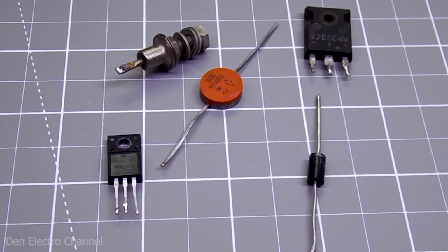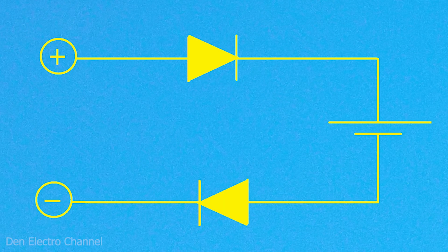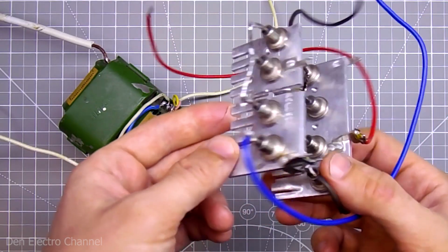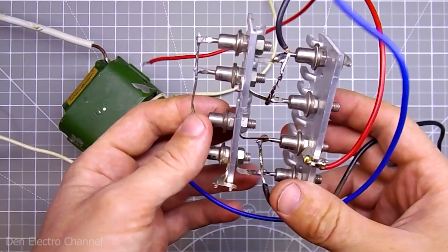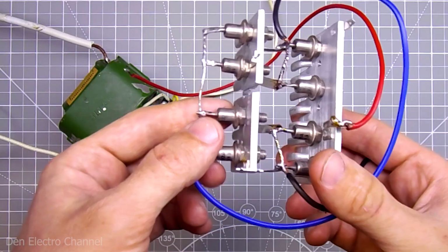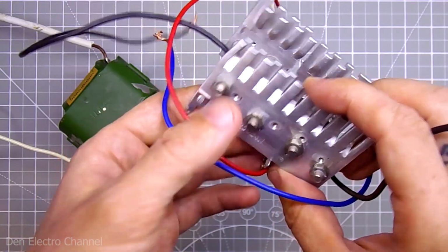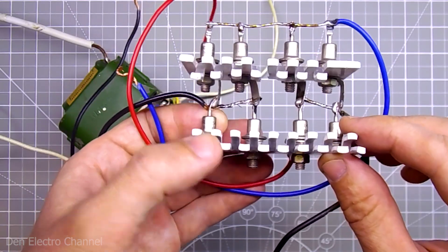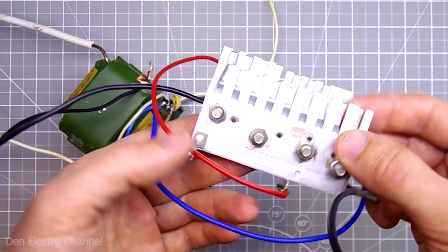In some cases, it helps to extinguish excess voltage, from several hundred millivolts if conventional diodes are used, up to several dozen volts if you take Zener diodes. This property of diodes is also very often used as a reference voltage. In other cases, when we use diodes as rectifiers, this property brings some problems. With a large voltage drop and high current, the diodes heat up very much.